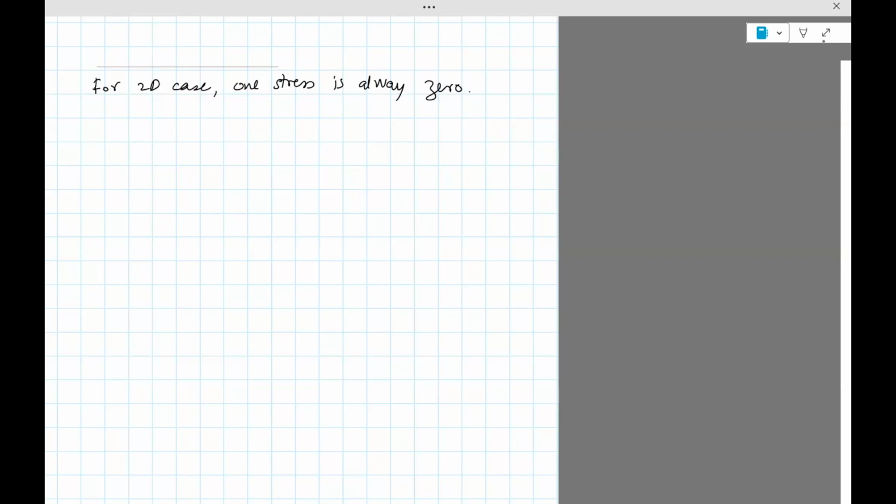So to give you an example, let's say that it's a plane stress element and you are told that the maximum stresses are 5 MPa. I'm just not going to put units, not very important here, and let's say 3 MPa. So this is like a plane stress element with principal stresses sigma A, sigma B, and shear stress is clearly 0 because those are the principal stresses. If you're given this, you still need to compute the biggest Mohr circle. So how do you do that, because you only have 2 stresses? Well, the third stress, we'll assume it to be 0.